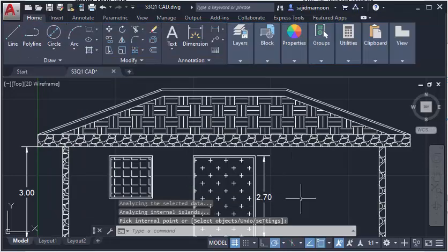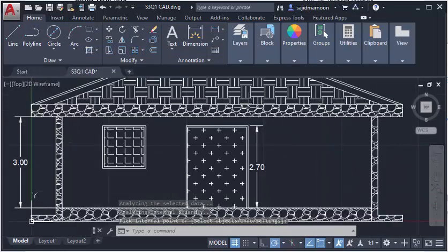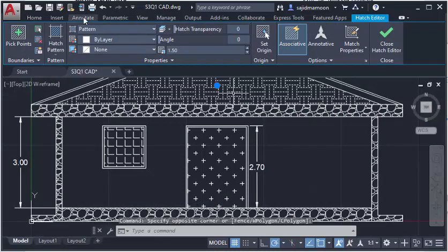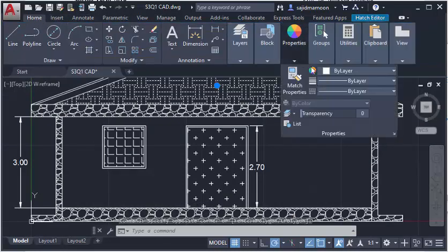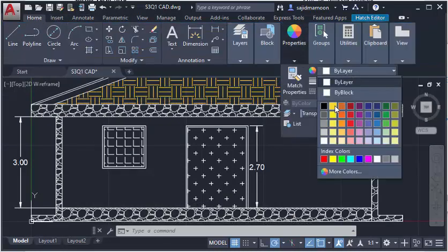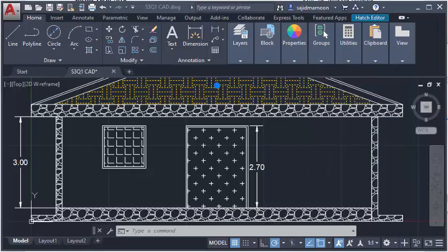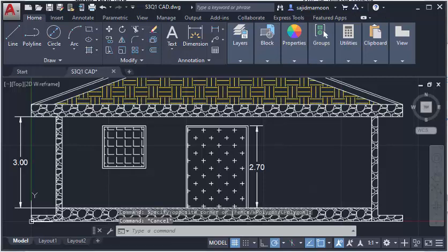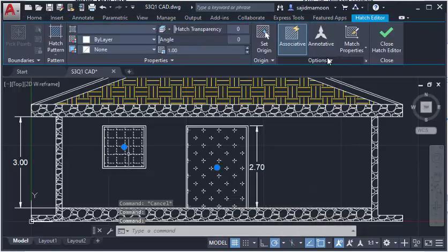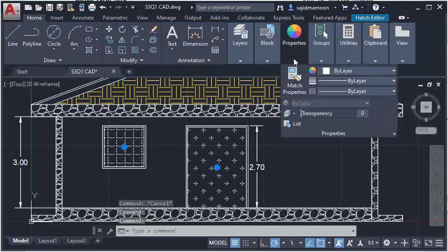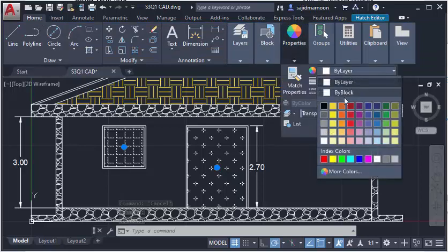Then for the color changes, what you can do is simply select any and go in the properties, and you can change the color, any color you want. What color is this one? Yellow. Then click escape, and for example this one and this one we need the red, so go here, home, color, and you can select the red.